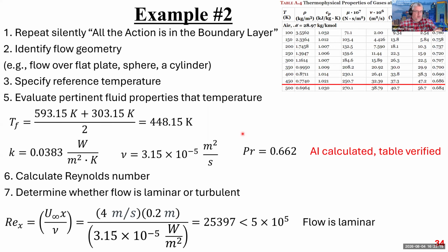All we're doing is solving for the initial heat transfer, right? So just that first moment. So no time dependency here at all, at least not for this problem the way that it's phrased. You could imagine an awesome problem that would include all of this, like transient heat transfer and conduction inside the plate. It's probably lumped capacitance, so probably not too hard. But you can imagine such a problem.